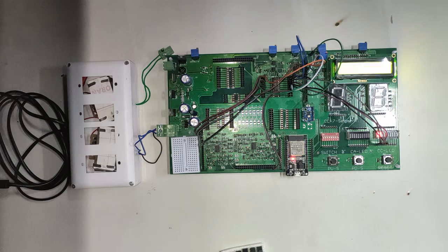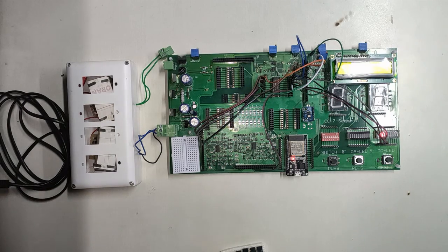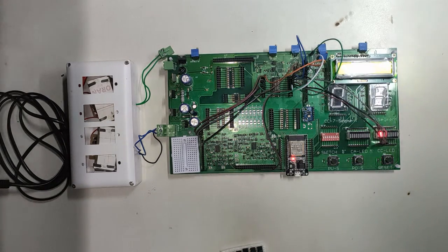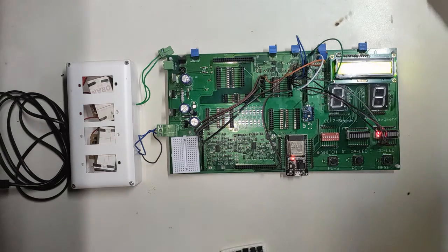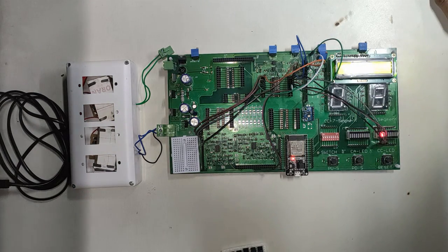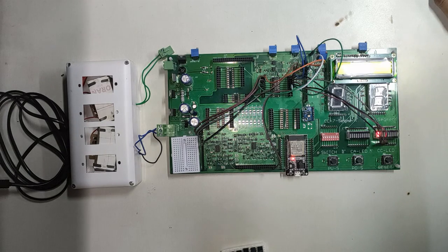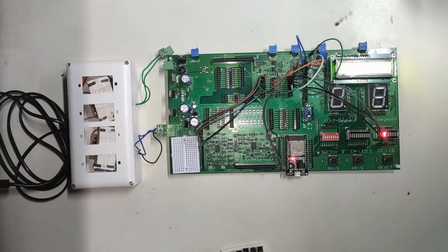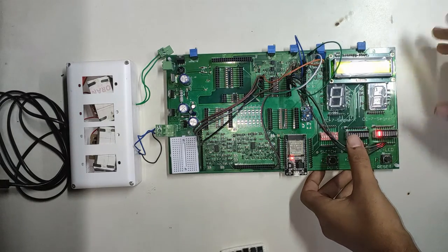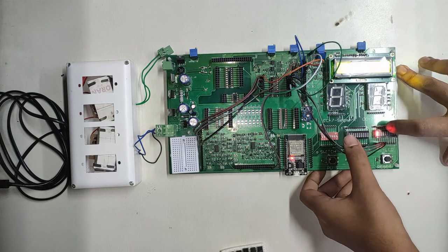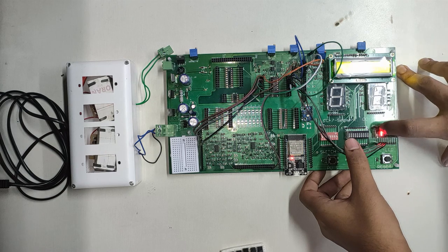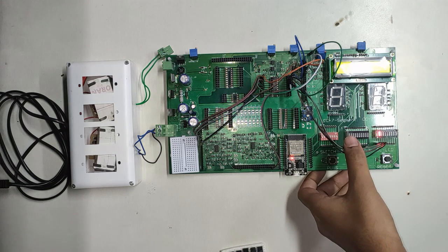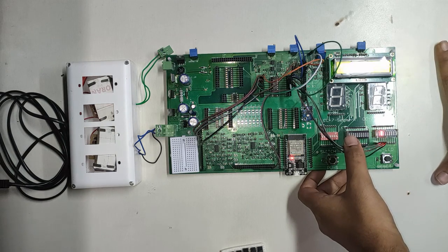In this part, we'll demonstrate how you can implement the shift register using the IC 74194. All the connections are given in the manual itself. Here we will just look at how our output looks when the input given is 0001, which is D is logic 1. We can see that the output is going from D to C, then B, and then A, which means that it is shifting towards the left hand side. So we can say that it is working as a shift left register.